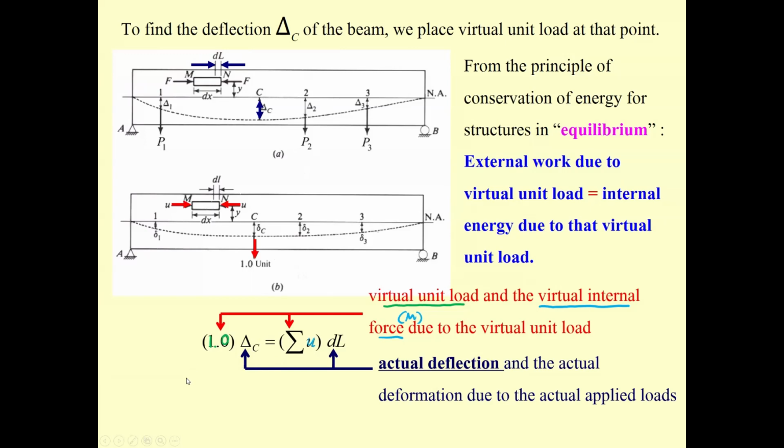And then there is the actual or real deflection. This is what we are looking for. For this one, you should be able to determine the actual or real deformation dL. So the procedure of the calculation will be, first, consider the structure.